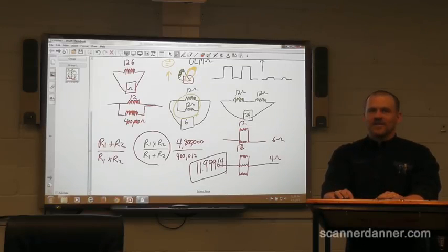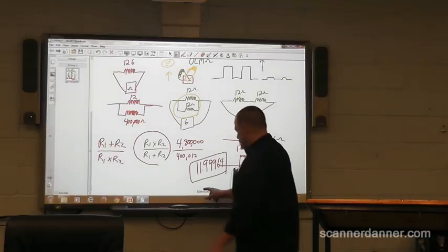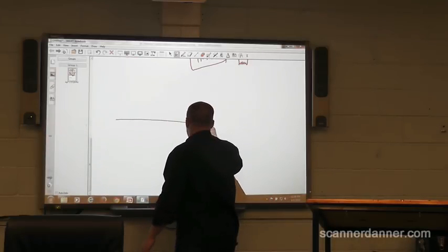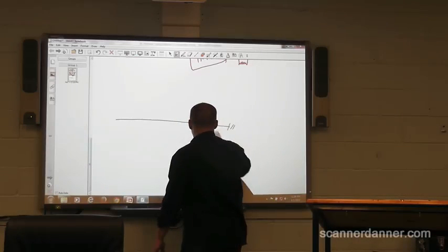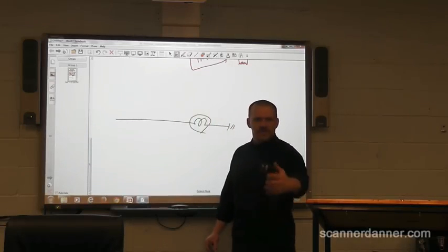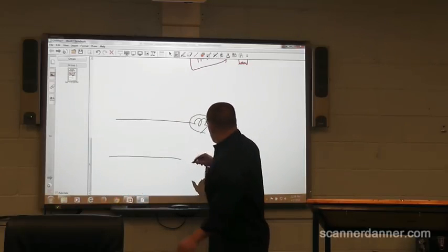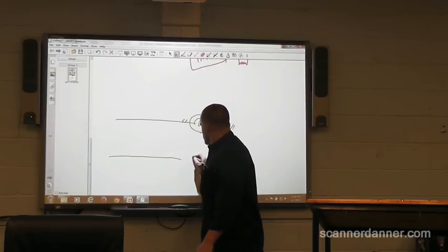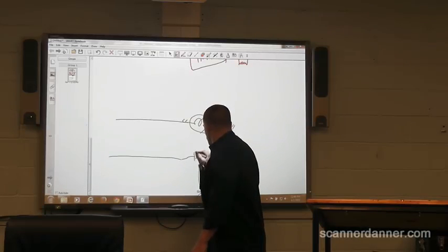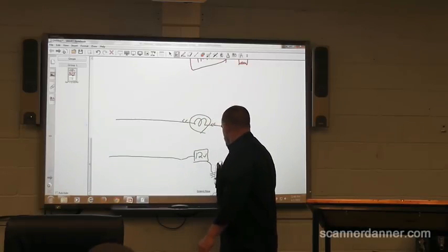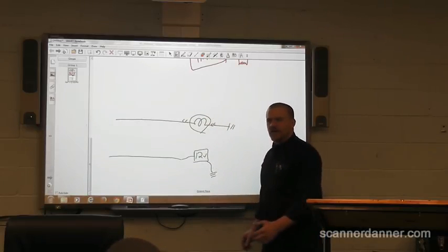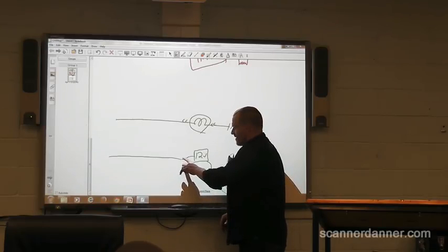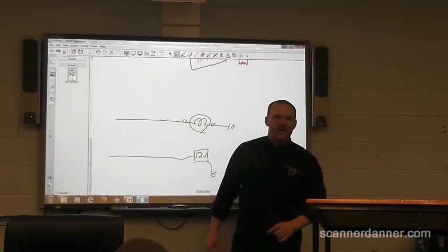I have seen circuits where your body's involved. You've got this 12 volt feed. Let's just use a light bulb. This light bulb does not light. Student's car. Take that wire off, disconnect the connector so you unplug it, and you read 12 volts on here with your meter. So your meter's connected like this to ground. That's a good feed, right? But then as soon as you touch that lead, that voltage on your meter drops down to 5.